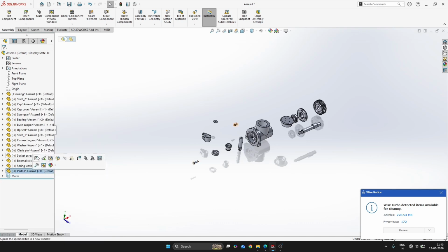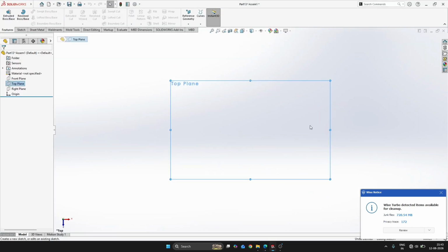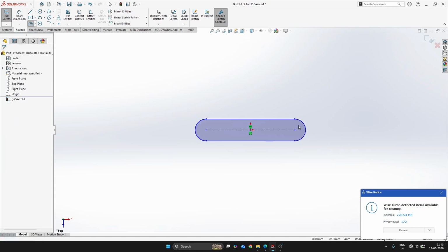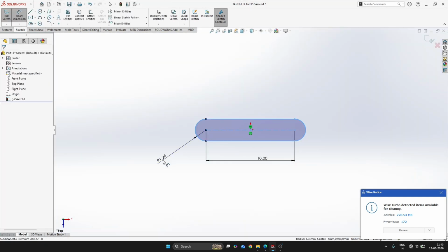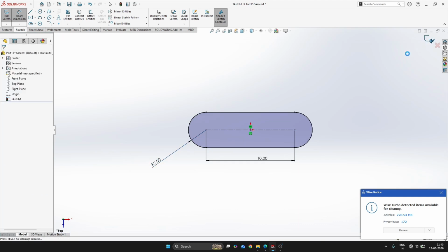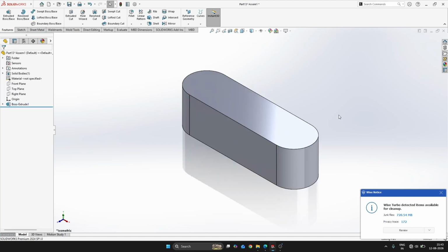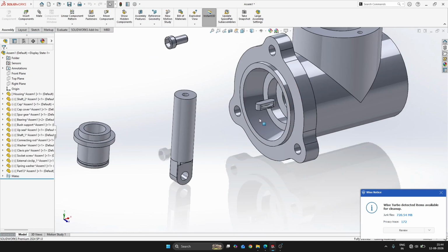Float. So keyway 10 to 4. Okay. Top line sketch. Use directly the key option. So this length is given, which is 10 only, and radius is given 2 only, and that's it. Exit. Control 7. Extrude 4. Enter. Yes. Save it.